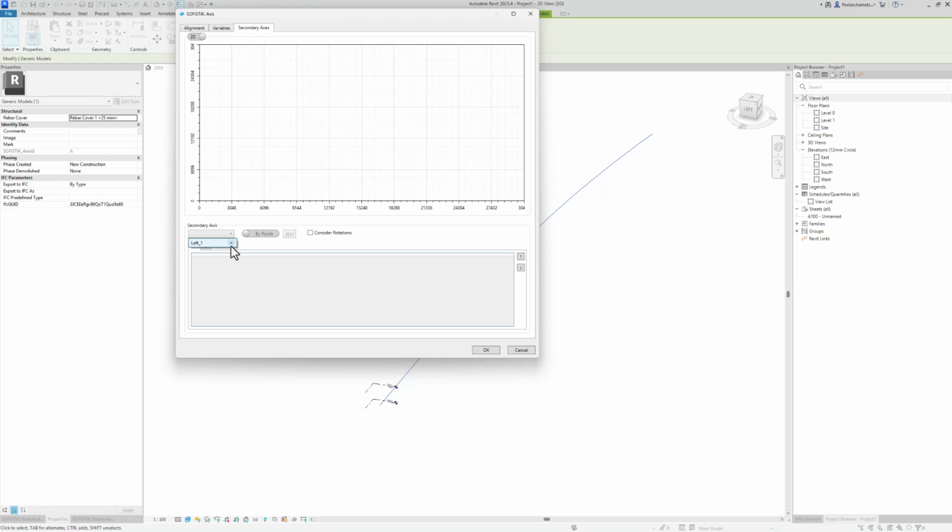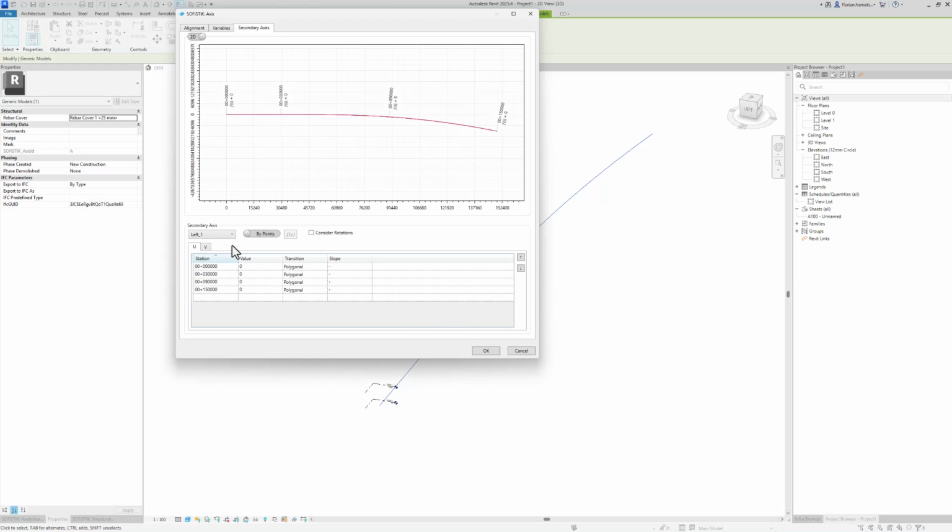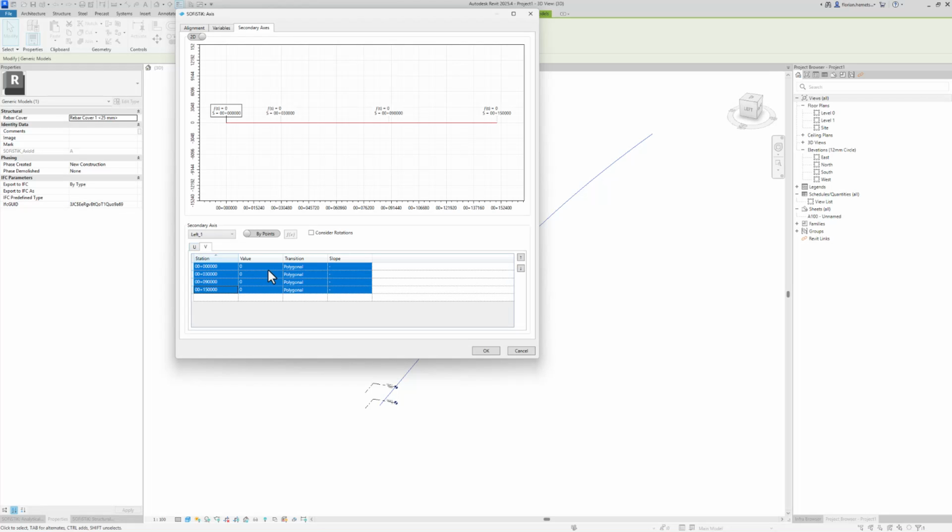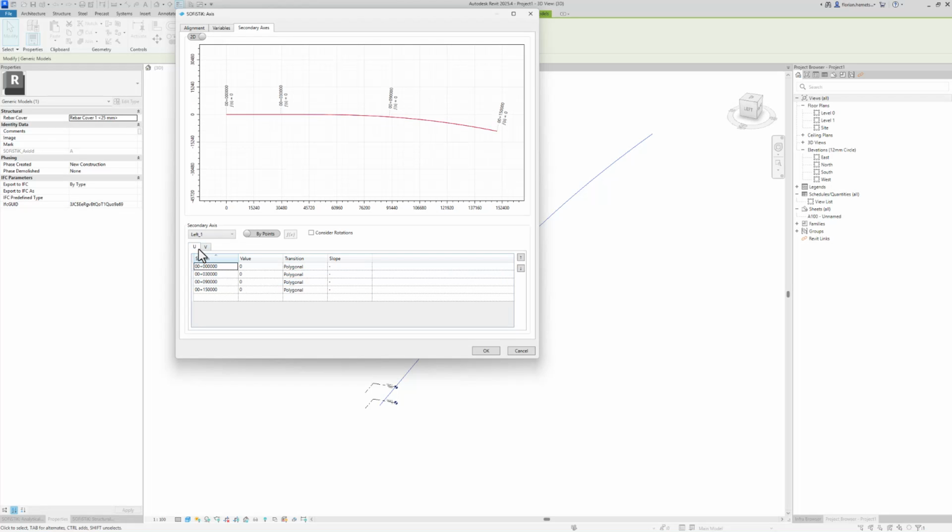Don't forget to click plus to create this axis. Down here you can find that the horizontal and the vertical offset is predetermined at the placement stations with a value of 0. The first axis that I want to create in the top view with an horizontal offset is with an offset of 3 meters.